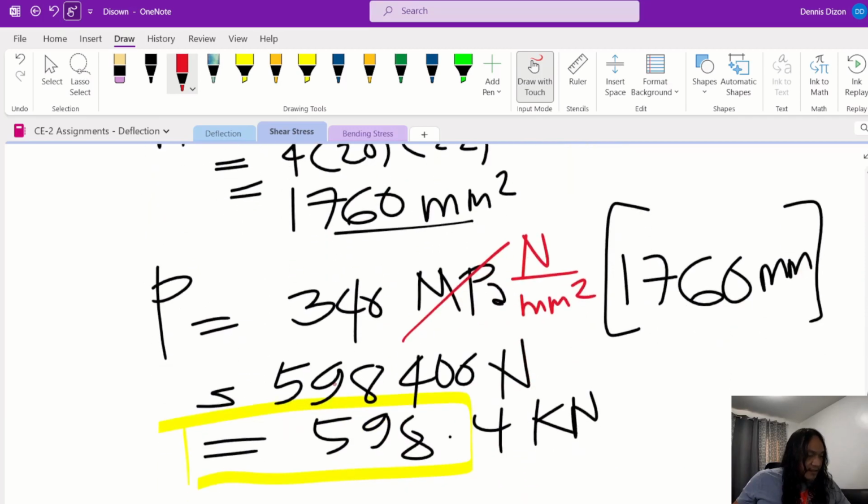I guess it's just a direct substitution. Just remember all those formulas, and then if it's punching, then consider the sheared area, the punch area. So that is the perimeter of your hole times the thickness. But if the question was compressive force, then the P would be the force, and the area would be the projected area, the flat surface, which is 20 by 20. But in this case, it is punching, and the sheared area is your perimeter times the thickness of your plate.